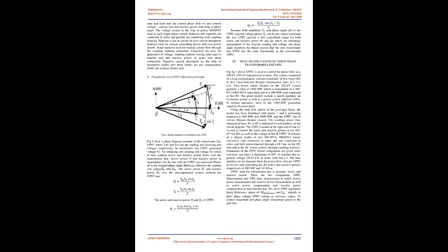UPFC is the most comprehensive multivariable flexible AC transmission systems controller, Mehtai et al. 2001 and Sen and Stacey 1999 [13]. 2. Transformer-less UPFC. Fig. 1 shows the transformer-less UPFC, which is built with the help of the CMI, cascade multilevel inverter, concept. We used power MOSFETs as the inverter function, with a combination of series inductor and parallel capacitor to generate a high voltage level. The coupling inductor is in between the series and shunt, a combination of inductor and capacitor.